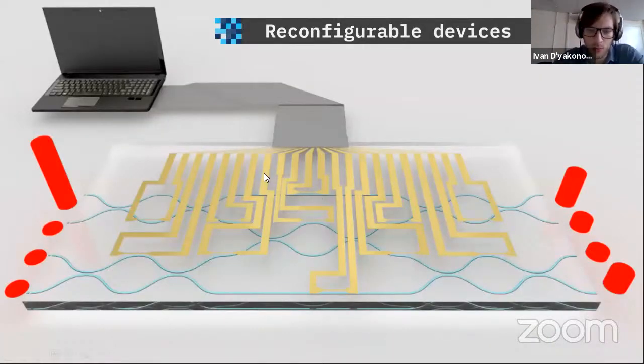So what do we actually aim to do with these devices now? We wanted to build a thermo-optically tuned device, which could be employed further in quantum optical experiments, for example. For this purpose, we had to evaporate a metal film on top. We found a group in our university who agreed to do that for us. Once we had the evaporation technology on this glass slab, we applied the so-called ablation process to remove some of the material from the top of the chip using the same femtosecond laser.